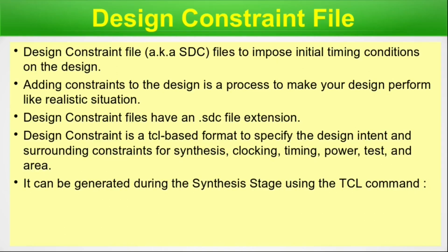It can be generated during the synthesis stage using the Tcl command write_sdc, then the path, and then the name of the file .sdc. This is a very widely used command, and it is used at the synthesis stage to dump all the constraints into a file. We can write the constraints as well as dump them. It all depends upon the tool which you are using. So don't think I'm making a global comment, but generally tools have this capability to read the SDC and write the SDC at the synthesis stage, and it may vary from one vendor to another. But just for your knowledge, apart from writing it by hand, you can dump it also.